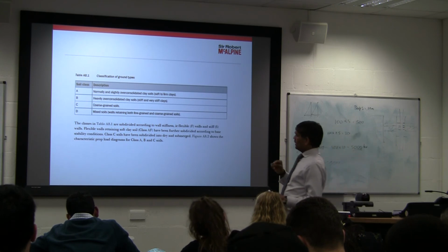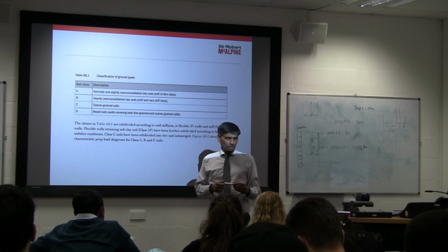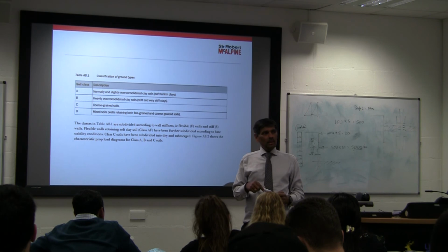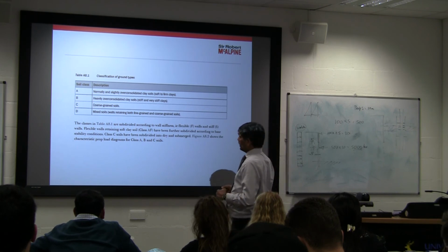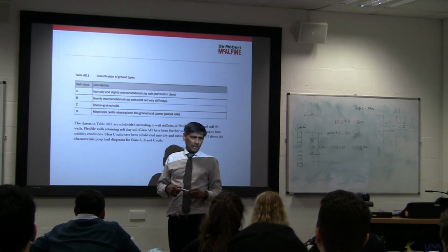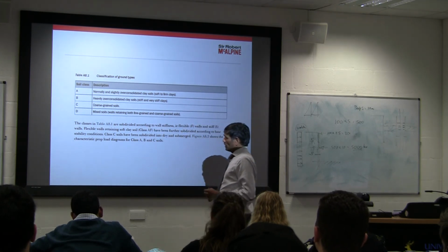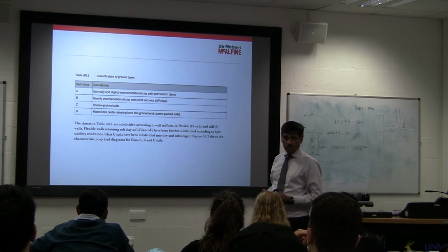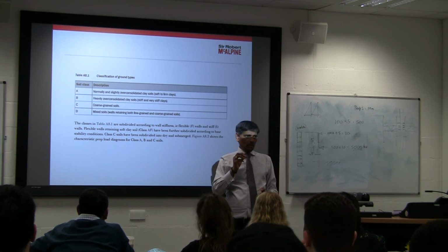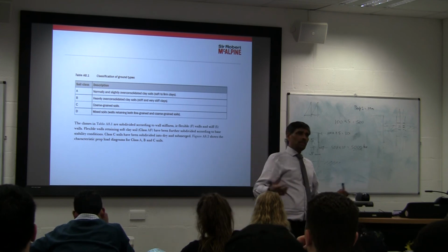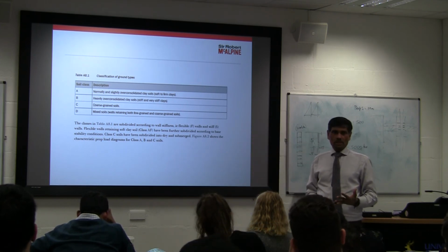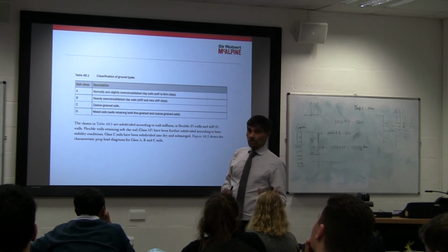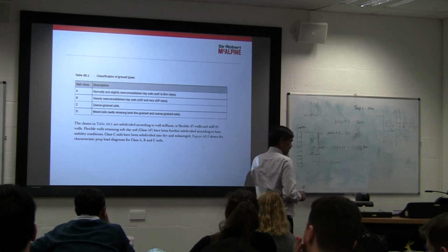So you will see, depending upon the type of the soils, that you get different distributions. A lot of measurements have taken place in London clay and also in gravels and across the site. And they classify that into 4 categories. A is normally and slightly over-consolidated, B is heavily over-consolidated, C is coarse grained, and D is mixed soils. So there are 4 classifications that have been done. So if somebody comes to you and says, right, this is my site, then you need to be looking at: is this over-consolidated? Has it got coarse grained material? Has it got a London clay that is very stiff? You've got to ask those questions and classify into those A, B, C, D.